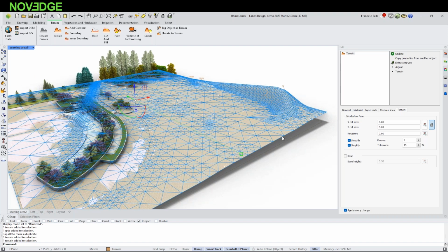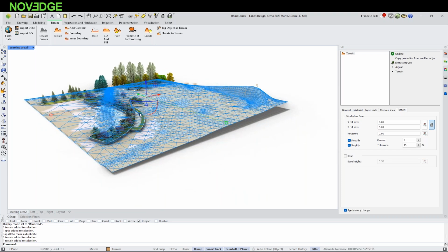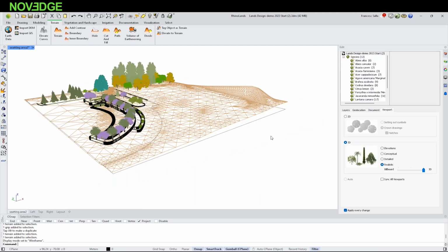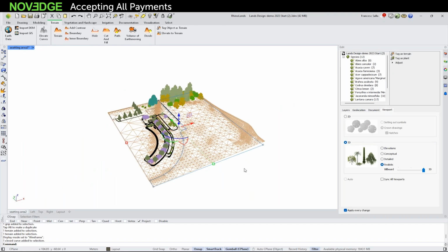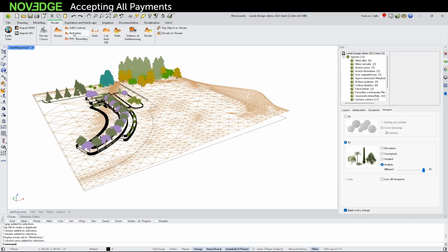Okay. All right. So the first thing I'm going to do, since I see that this area is overlapping with an existing surface or zone that I had underneath, is trim the terrain from an existing curve. I'm going to switch back to wireframe for a second, because here I have a boundary curve that was previously created, but I'm going to use it to trim the terrain and define the new boundary for the terrain. So here I've got a command that will let me do that. So I need to select the terrain. Just notice that here in the command line, whenever you run a command, you just need to follow the instructions indicated here. So it's pretty user-friendly to run any command without any previous experience.